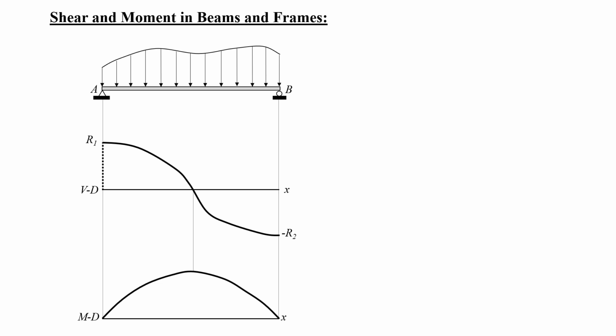As we go on, the explanation why the maximum moment occurs at the point where shear is 0 will be clarified or emphasized. So we consider two sections in the beam at distances x1 and x2, and we consider a differential element dx so that the loading over that length dx would be uniform at w, or negative w, because w should be negative. Then the thickness is dx.